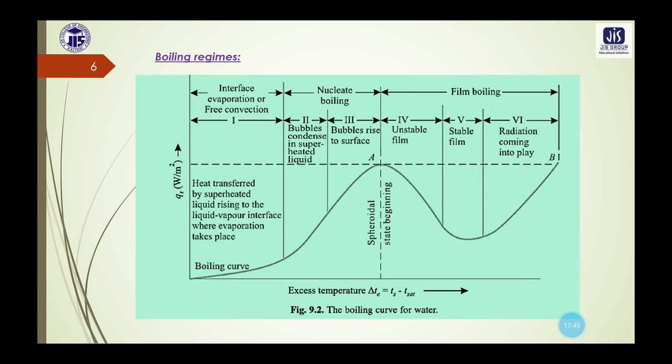This nucleate boiling is characterized by the formation of bubbles at the nucleation sites and the resulting liquid agitation. This bubble agitation induces considerable fluid mixing, which promotes a substantial increase in the heat flux and the boiling heat transfer coefficient. So this is the concept of nucleate boiling.